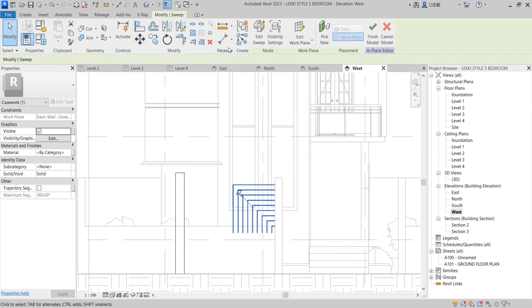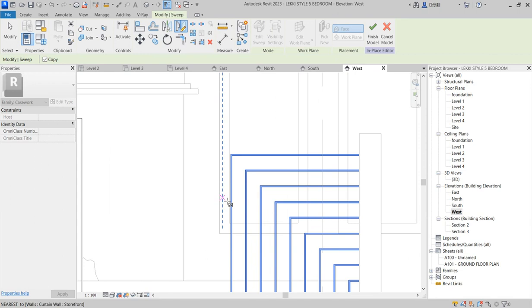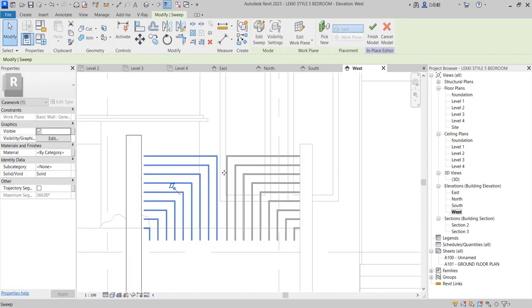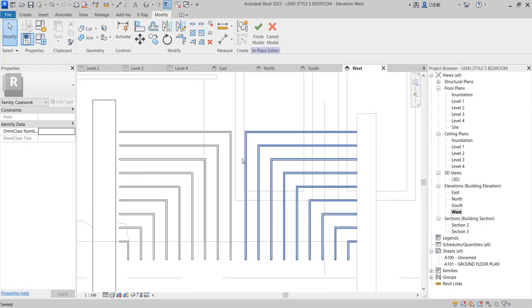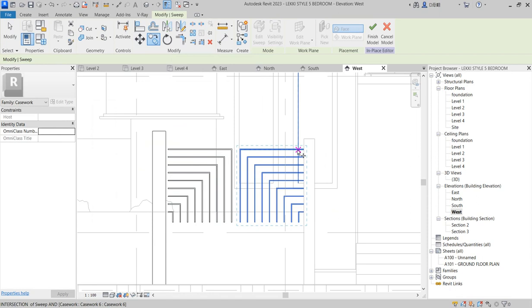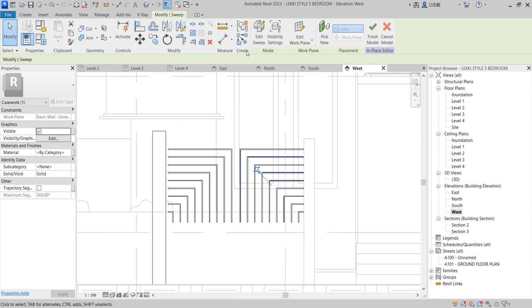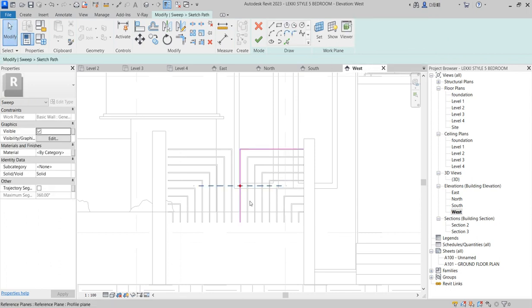At this junction now, what you need to do is to mirror it. So mirror this part for yourself. Good. As you've done with the mirror, what you need next is to create what will connect them together. How do you do that? You can still use this particular one to do that. Copy and say just one. Press that and you say edit in place. In edit in place, this is gone, delete this guy.